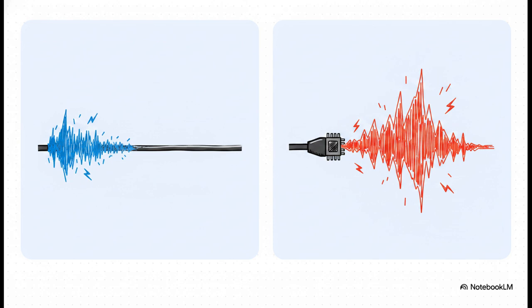So if you want a cable that's actually long enough to reach from your PC all the way to your VR headset, you are going to need an active cable. These cables have literal silicon chips. They're called retimers and redrivers, embedded right inside the plugs. A retimer will catch a dying, degraded signal, extract the core data, and synthesize a brand new, pristine signal to blast down the rest of the wire. It's literal silicon necromancy, resurrecting your data from the dead.